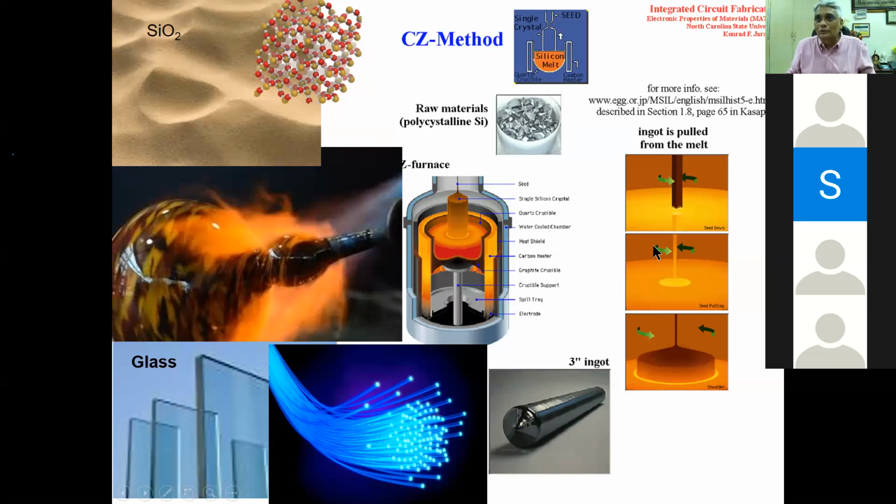You melt it, you slow cool it, the Czochralski process, and then you slice it. First of all, it is tested by X-ray diffractometers to see the quality on the entire length, and then you find a crystallographic axis and you start cutting them. Only then do you get a wafer like this. So what we see now finally in this form, right? Shiny silicon wafer.